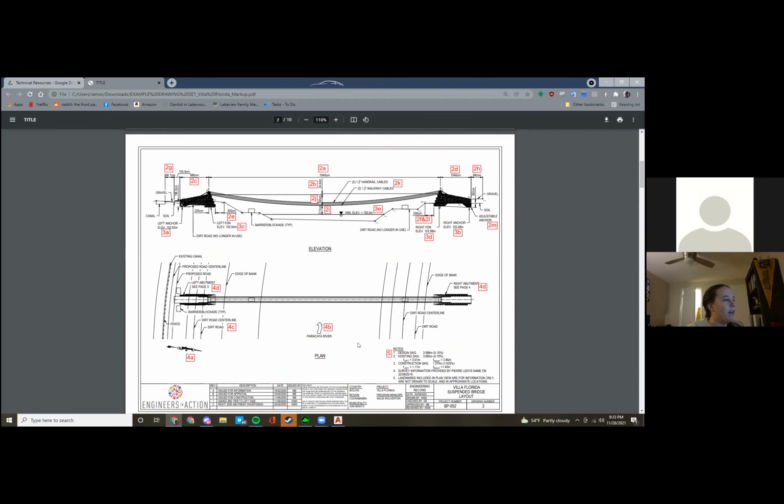The second page, we've added more to this notes section, since now we have a required check for the construction sag. And so in the field, there is a limit to where we want you to hoist the cables to. Typically we pull the cables really tight so that they can sag over a time period, and then we lower them even more, but we don't want to pull the cable so tight that it's going to break the winch and cause a failure. And so part of the calculations now required is figuring out what that point is. And so we want you to also put that on the drawing. So that's what this construction sag is.